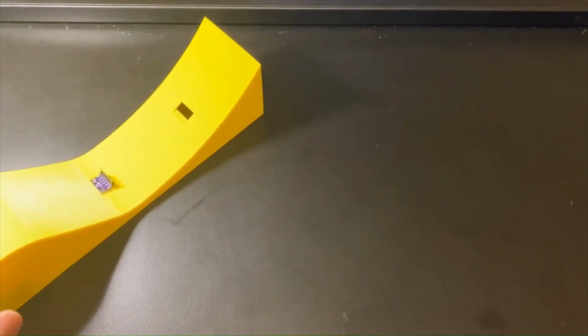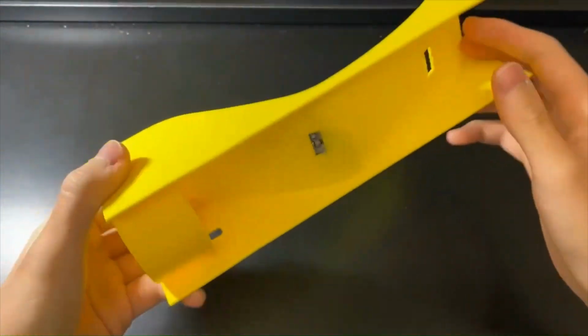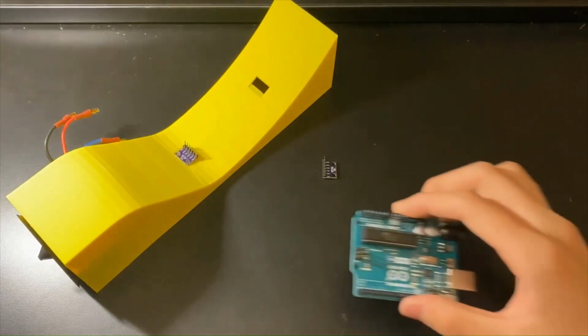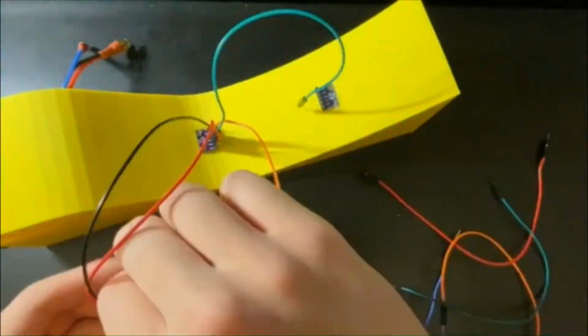Well, this prototype is only producing a tiny bit of downforce, so it's probably halfway to its failure. But what's the problem? We need actual experimental data to know what problem we have on this prototype in order to get a better design, a better version. This time, the choke is lower and the diffuser becomes wider to prevent airflow stall. This BMP280 is a pressure sensor to collect the data inside the tunnel. And lastly, an Arduino Uno board is utilized to control the sensors. Now, install the sensors and wire these things and it is ready to test.